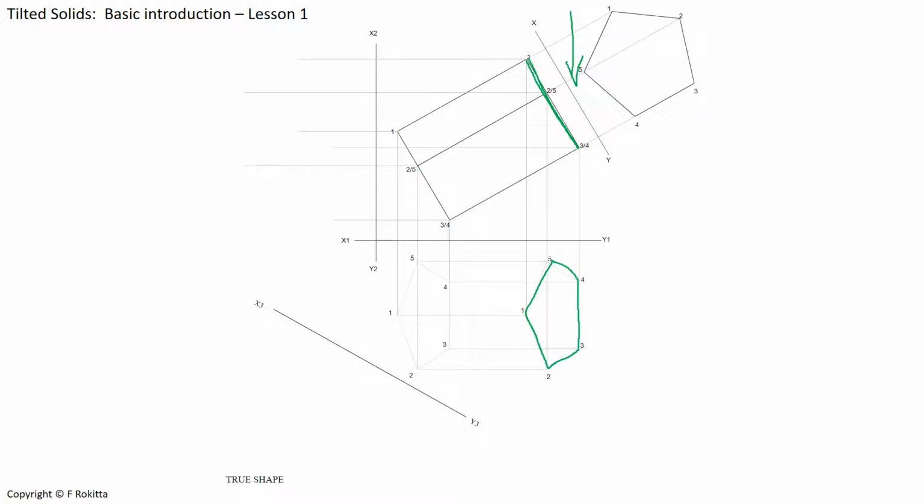It also means that the outer edges of the prism on the top view will be solid, because the outer edge of an object will always be drawn in solid, and number 1 is seen first when looking down on the top view. So if I were to go back to the front view and look down onto it, I will see the corner number 1 of my prism first, and therefore we know that 1 and 1 on our front view and top view will be solid.